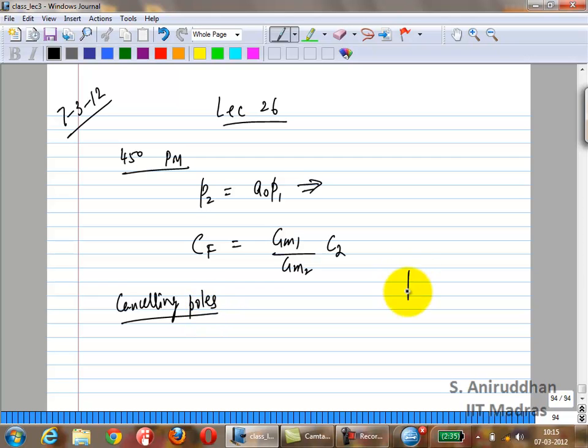Okay? So you have P1, you have P2, and maybe you have P3, and you are going to put your 0 here, right on top. Okay? So that once you cancel it, your effective transfer function is only going to have two effective poles. One is P1, the same as before, dominant pole which sets the omega u. The other one is going to be P3, which is actually much farther out. Right? So your phase margin is going to be much better. Okay?